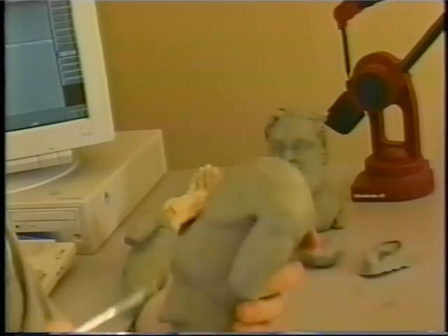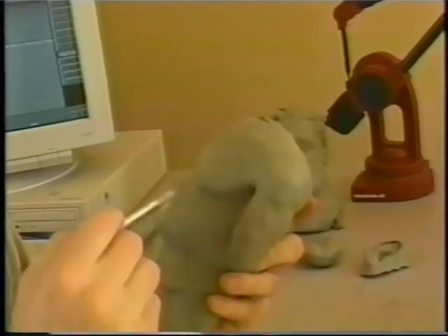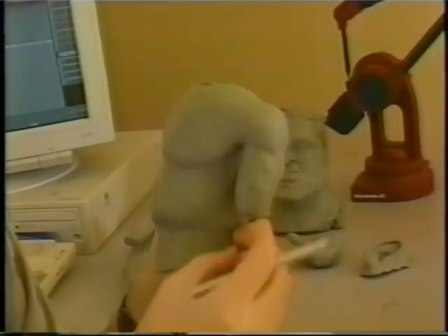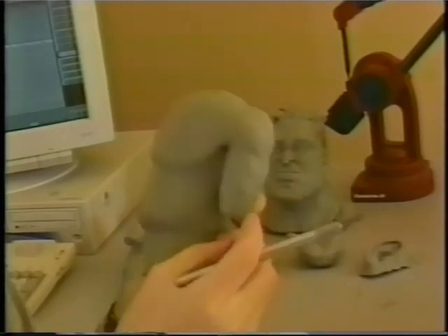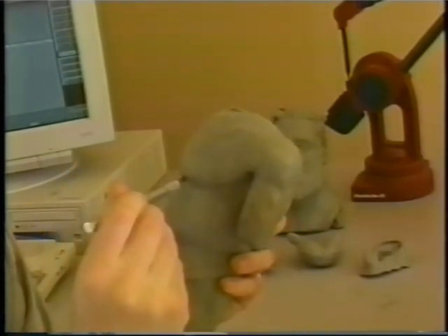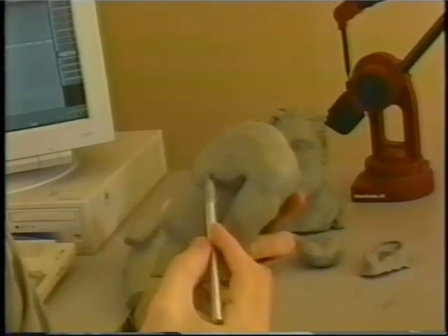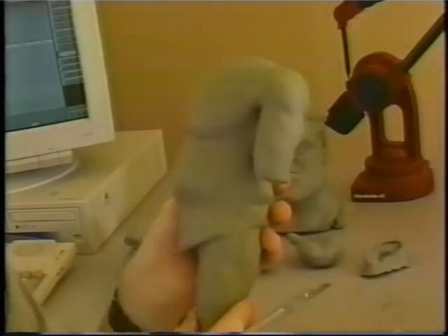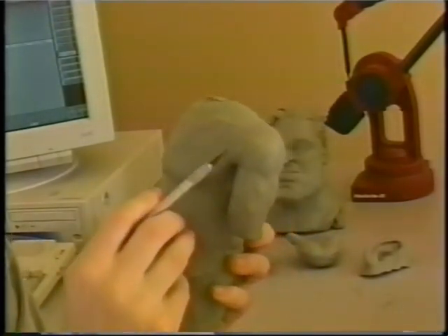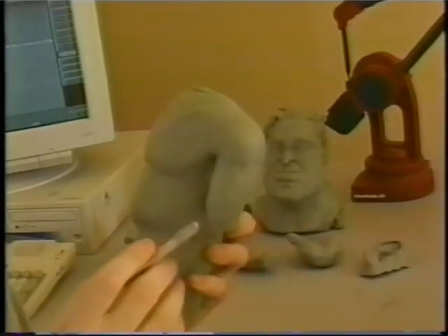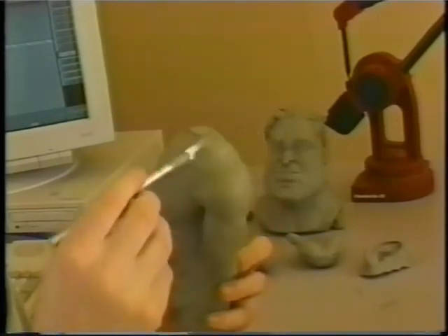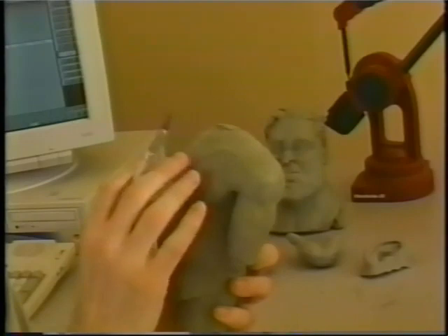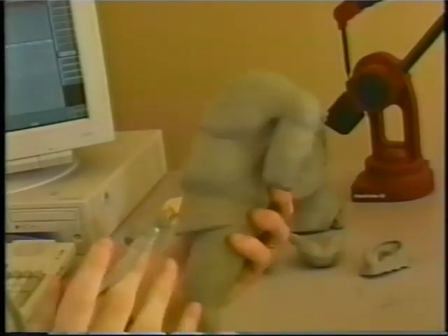Another thing you can do is do creative things for lining up geometry going different directions. So in this case, the chest all the way down to the arm to the wrist was one surface that wrapped around the shoulder and comes down. And the break is right here in the chest. And that surface actually went underneath, all underneath here, and came up back on the other side. So this thing was one continuous surface. And that means that this shoulder part, which sees the most amount of bending during animation, is going to be clean and not going to show. For instance, the normal way would be to have a blend here coming off of there. This would be a separate object, and you would somehow connect it to this surface.